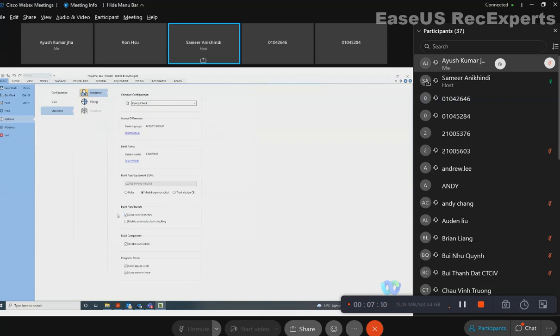If the pipe route is complex, it will give you some very weird route. But if the pipe is straight, maybe a few bends, it may give you some decent route. So just use it whenever you require. And it can also clash check while auto routing. Means if the route is obstructing somewhere, it will take some bends and do the clash checking. So let's see how it looks with this option.